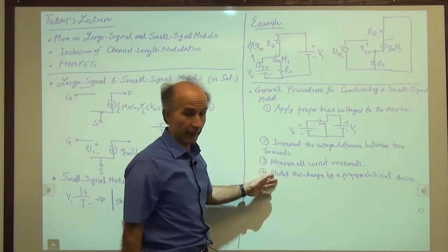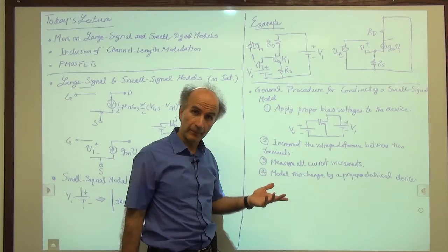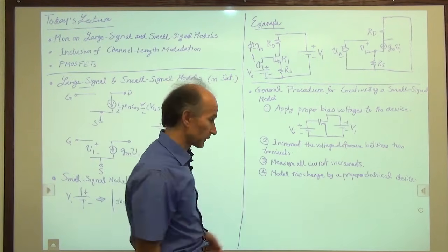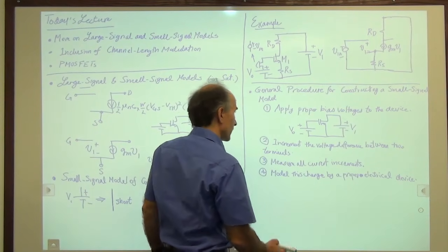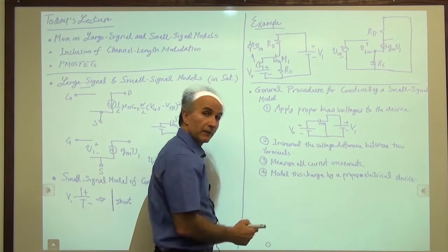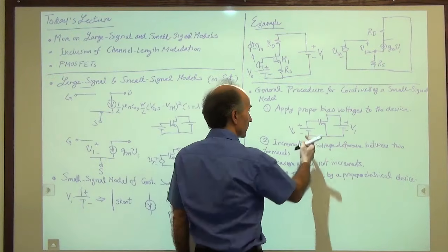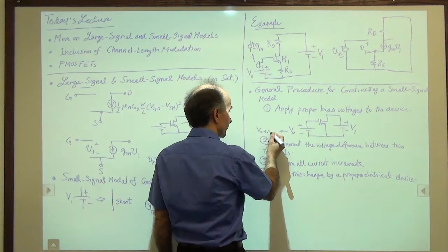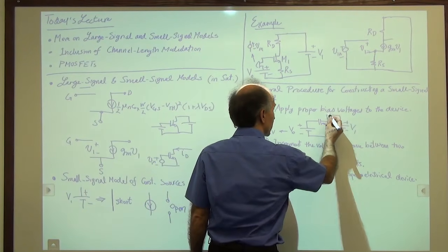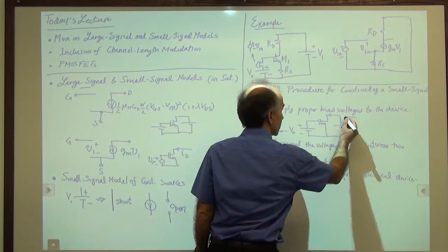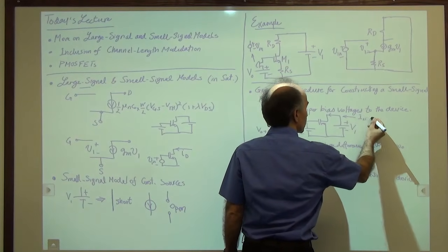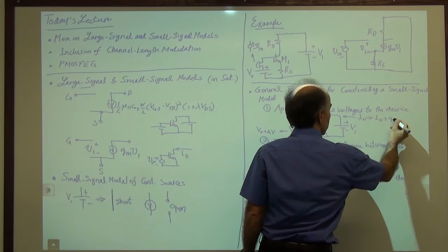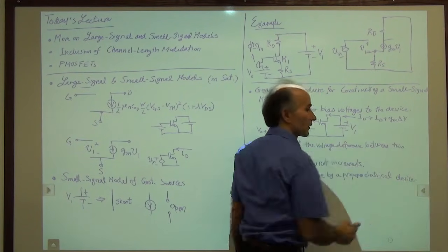Okay, so we have already done that, for example, for gm, I should say for this simple small signal model that we derived. Because what we did was, we said if this voltage changes by delta V, so if this goes to V0 plus delta V, then we saw that this current changes from ID to ID plus gm delta V, assuming everything is small.